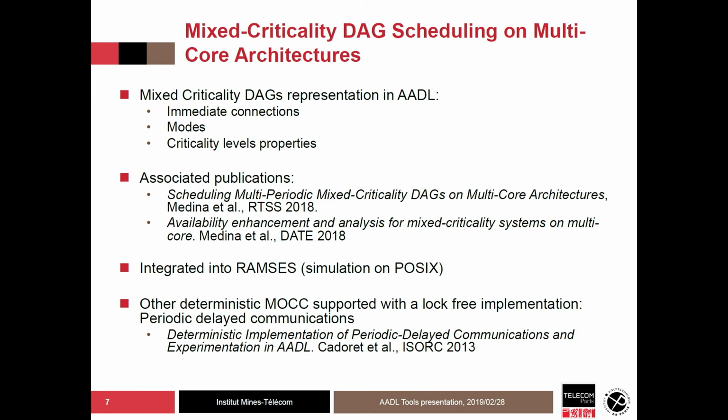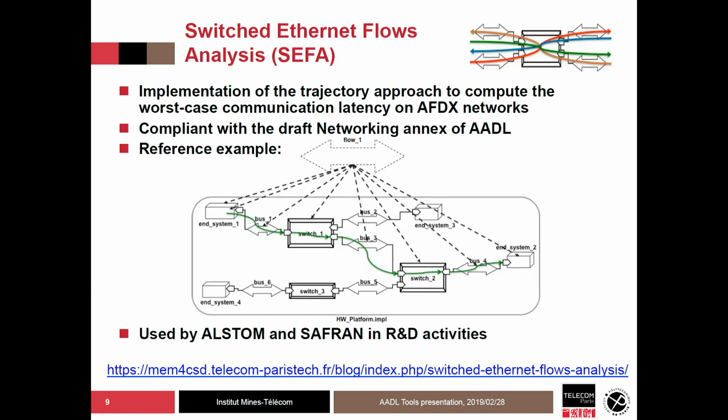So I'm a bit late, so I'm going to pass a bit on this. It's more on research work that we have done in 2018, and that's been integrated in Ramesses. But the potential transfer is a bit far away for now, so I'm going to focus on that part instead, which is the switched Ethernet flow analysis technique, which means we have implemented an analysis tool for AADL to analyze worst case end-to-end latency on switched Ethernet networks, which means typically AFDX networks, which stands for Avionics Full Duplex Ethernet.